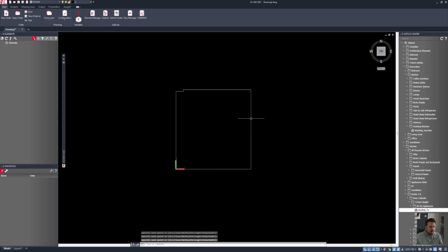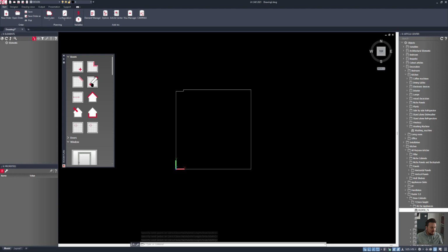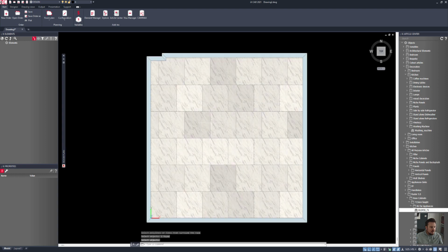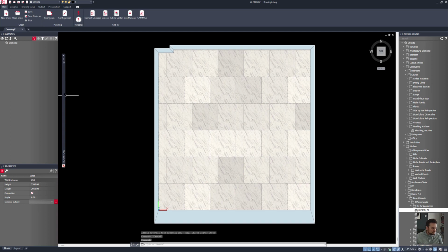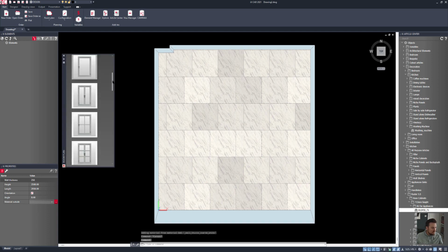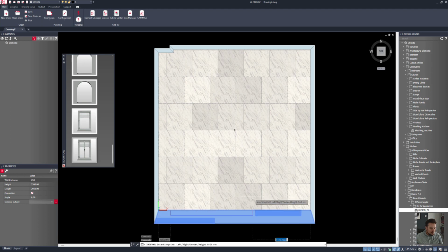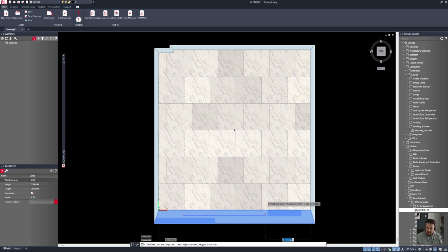here in the corner. And I need to add in my walls now, so I'll just click on the pencil tool and that will now create my room. I'll make this wall down at the bottom a little bit deeper, so let's say that this is 250 millimeters because this is an external wall, and then I want to add in my window, so I'll come down and find my preferred window of choice, and I'm going to set that window there 600 millimeters from that corner. It's actually a little bit more, so let's make that more like 800 millimeters from the corner.